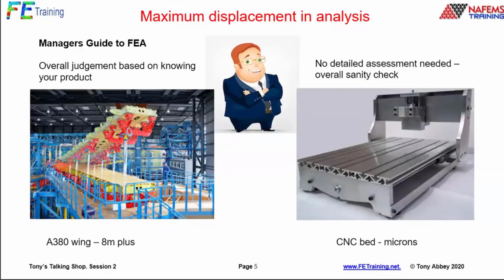So I recommend that for somebody calling in saying they don't know very much about FEA: hey, you know your product. So that's our first check. First sanity check, is the number about the right order? Again, no calculations, no knowledge of engineering or FEA needed. So that's my starting point, and that's a great way of starting to filter down the result.